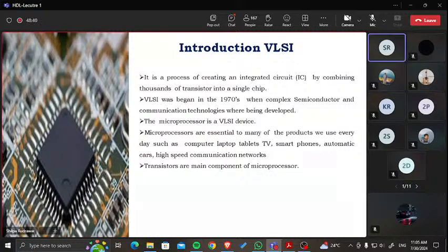This is not a part of this particular subject, how it works, but at least you should be able to recall that there are source, gate, drain terminals and one substrate or body. Whenever you apply gate voltage, a physical channel will be formed, and once the channel is formed, electrons will move from one direction to another, and that's why there is a flow of current and your device will turn on. So small voltage controls large current, that is the drain current.